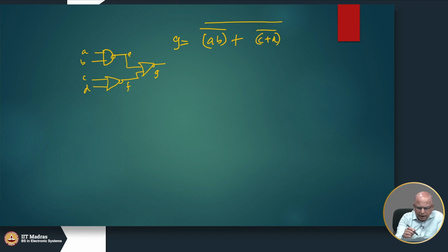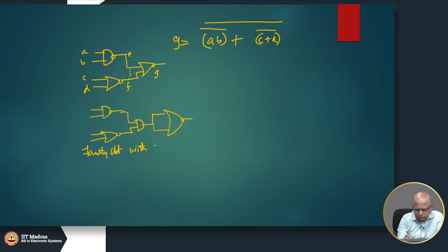And if there is an AND bridge between the two, then the circuit will produce, remember there will be a fictitious AND gate in an AND bridge. So this is a faulty circuit with a bridge fault, E bridge F. Sometimes we write it like this, E bridge with F, which means there is a short circuit between the two. Okay, this is an AND bridge.